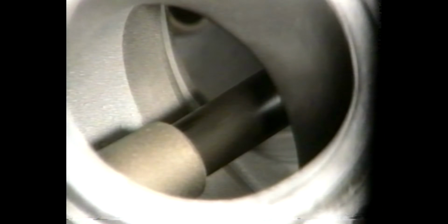The second type of profile is called asymmetrical, where the shapes of the opening and closing ramps are very different. In most cases, the design of the opening ramp forces the valve to open very quickly, reaching maximum lift rapidly, and keeps the valve near maximum lift for a much longer time. This dramatically improves the flow through our heads. The shape of the closing ramp lowers our valve slowly, which greatly reduces the stress on our valve train. Most high-performance Evolution and shovelhead engines use asymmetrical cams.